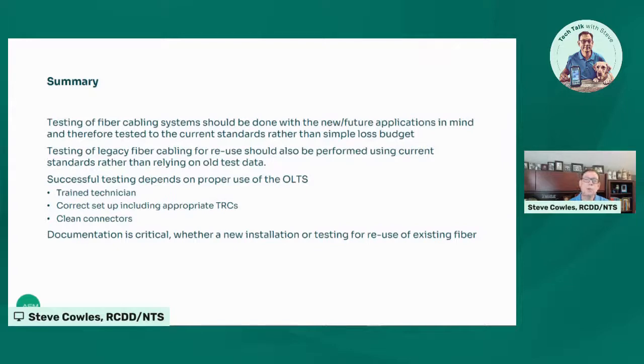Successful testing also depends, as we mentioned before, on the proper use of the optical loss test set. So you've got a trained technician, you've got a correct setup, including using the appropriate test reference cables, not having a mismatch, not having test reference cables that are in bad condition or otherwise damaged, and that your connectors are clean. So remember, inspect them, clean them, and inspect them again to make sure that the cleaning worked.